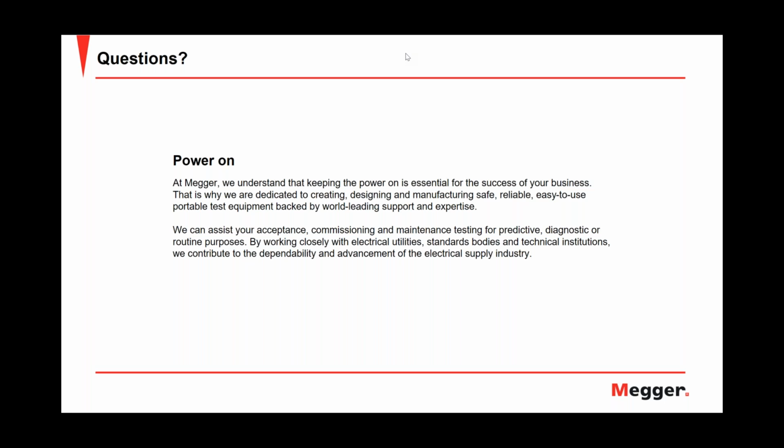That's one thing. So the chance of really hurting the insulation is pretty much not there, because a lot of people ask this question, since they know from the cable testing world that solid dielectric cable should never be subjected to DC testing anymore, because you will damage the insulation. However, that is a different test. That is a pressure test, 30 minutes or longer at substantial overvoltage.